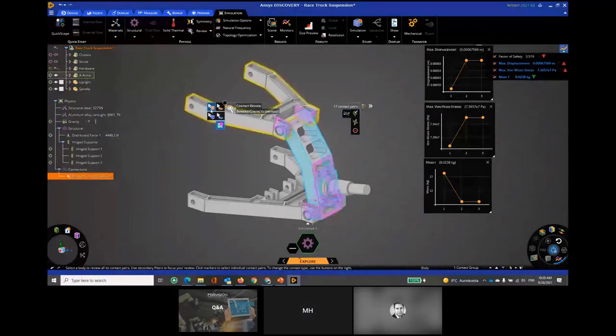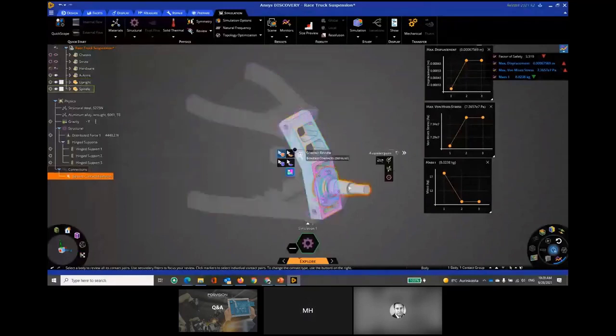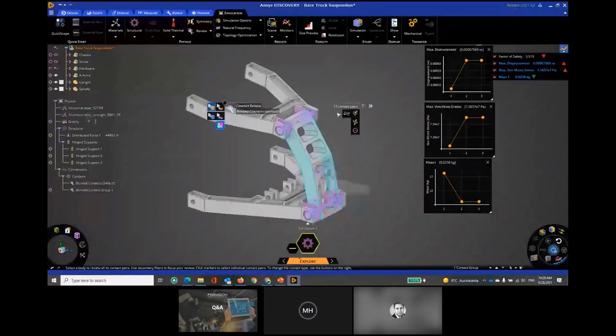How does this system work here? You can select either bodies or surfaces. So let's select the bodies. If I click this one, I get all the 4 contacts which are associated with this particular shaft. And I want all of them to be permanently bonded connections. Now, as you can see, there are 13 contact pairs left from the initial 17.